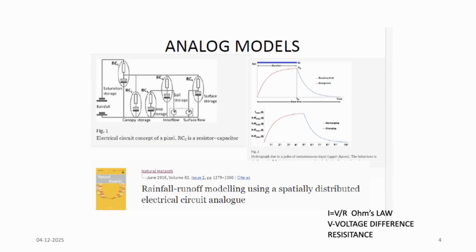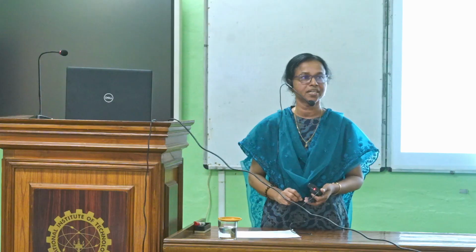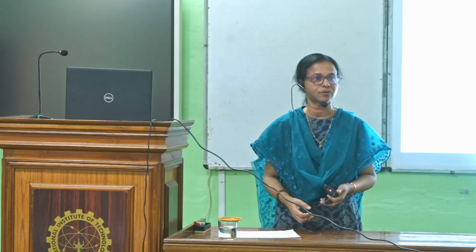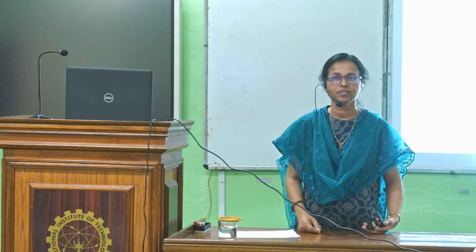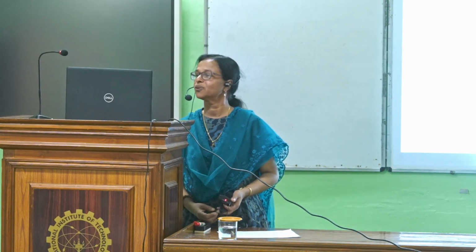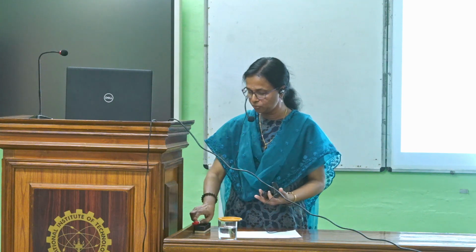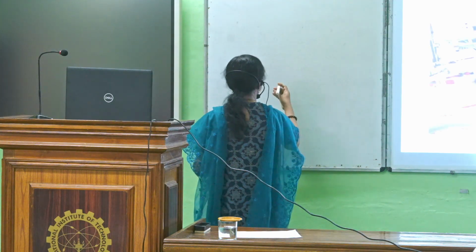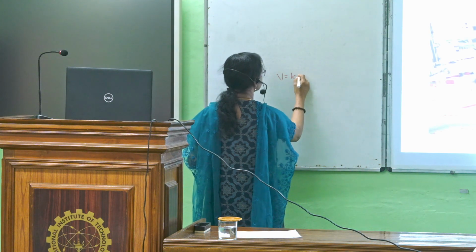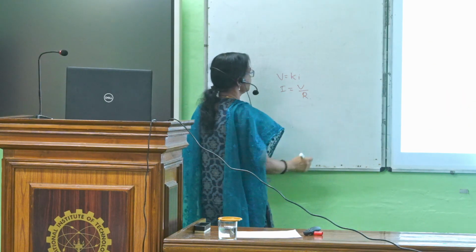Then what about an analog model? From the name itself, something is analogous. If I take groundwater flow, what is the basic governing equation? Darcy's law: V is equal to K into I. Suppose I take Ohm's law: I is equal to V by R. So how are they related?